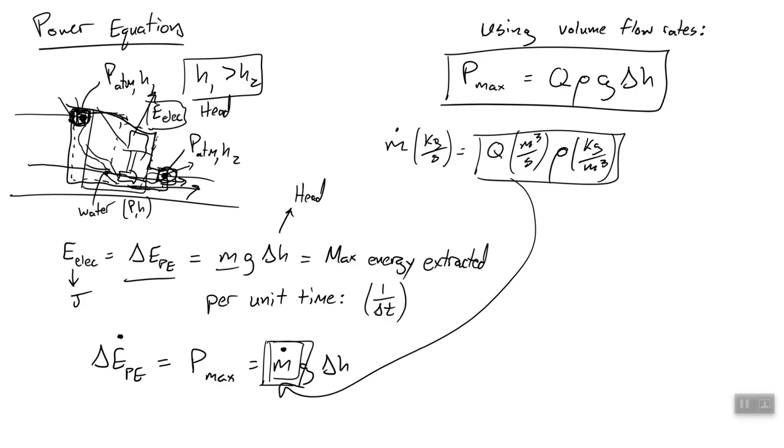So that is the maximum power you can get out of a dam, accounting for the head of the dam. We see why head is important. Gravitational constant, that is a constant, not going to change. The density of water, generally the same. And the volume flow rate of water through our dam, which we control. Just drawing our dam again, the side. Remember that gate? Well, changing the volume flow rate is as simple as moving that gate up or down.